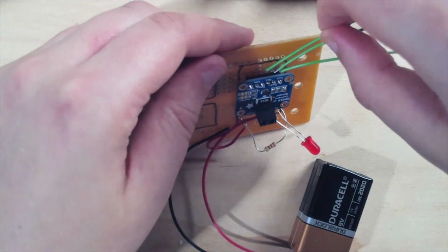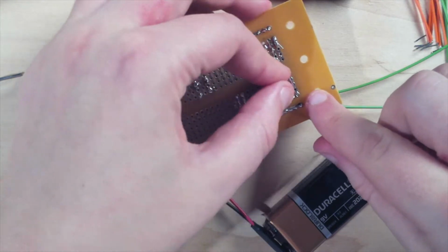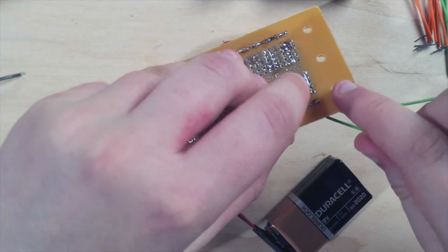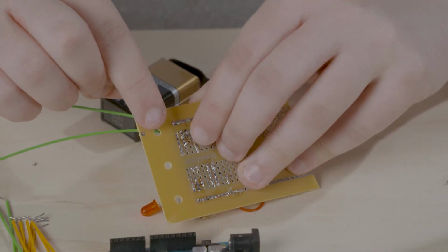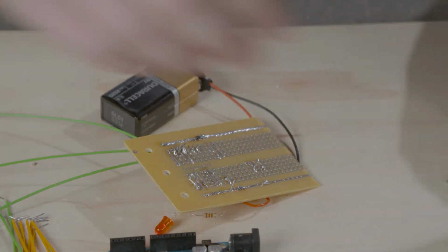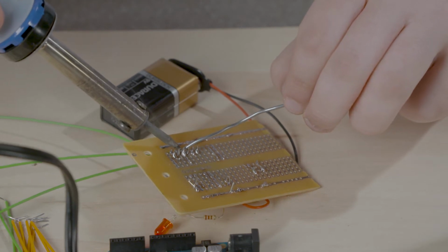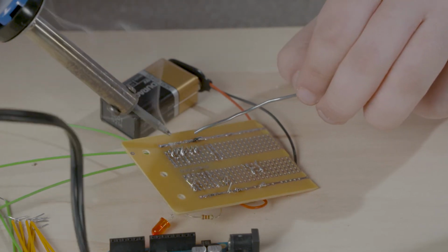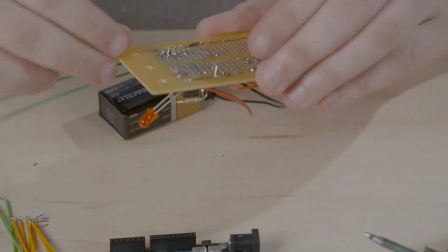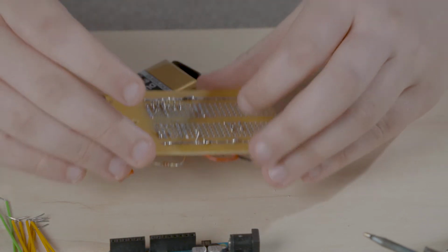We're going to put the wire in the SCL hole and bend it towards the correct pin, as best as you can. Now carefully solder it. There. Let's check if it's good. Nothing touching unless only the pins that we want.